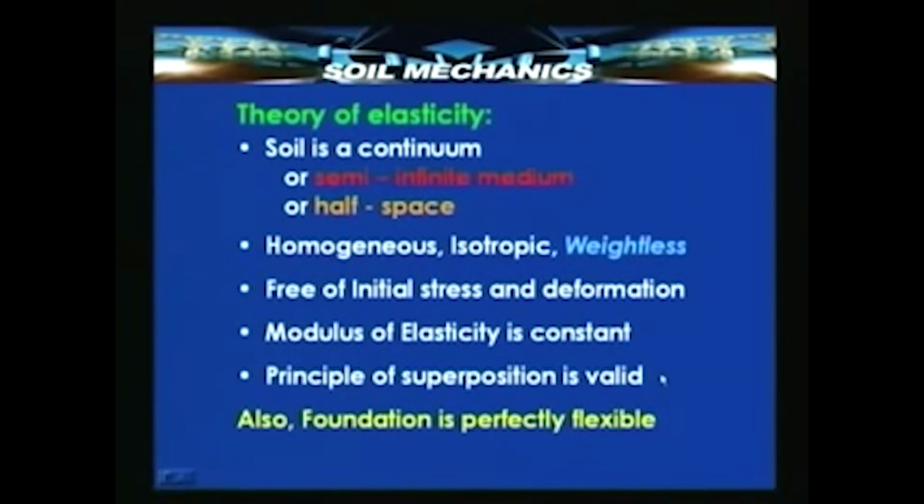That means, if by chance there are two loads applied over the soil, the stress due to the first load and the stress due to the second load can both be added in order to get the total stress due to both the loads. This we had in fact discussed indirectly a while ago. For example, if we want to know the total stress which comprises the stress due to the externally applied load and the stress due to the self weight, then we assume that the two can be superimposed in order to